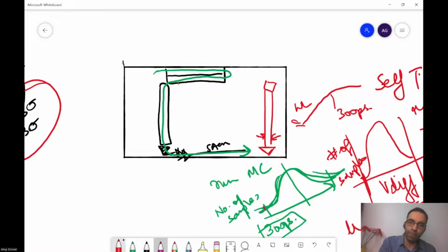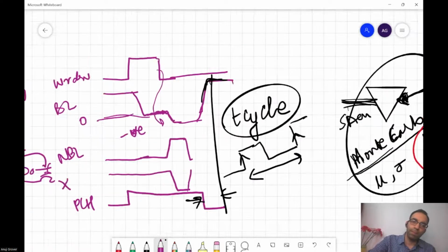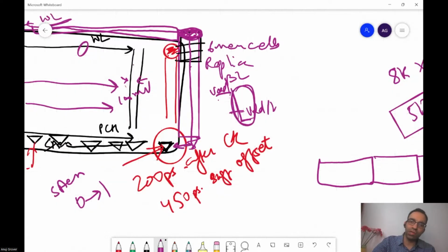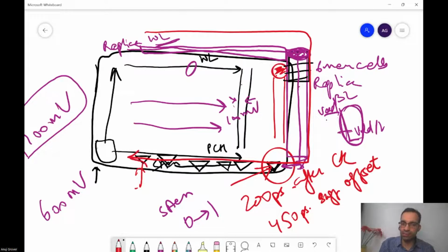This is the replica word line, replica bit line, and so on. So in the beginning of the class, when I showed the replica path over here, I had shown that replica word line will go like this and select bit line, and then SAEN will come like this. In reality, this means that horizontal delay will come twice. Are you able to see this?